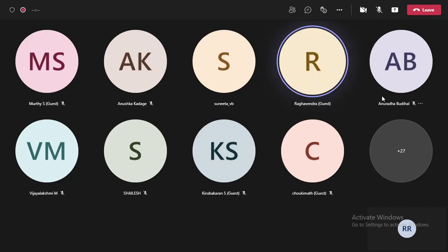Right. Okay. Good afternoon, everyone. It's Raghavendra. As promised in the morning, I'll be giving a very brief overview of how we've implemented the physical layer portion of a VLC system, where VLC stands for Visible Light Communication. So basically, in this system, we take up an LED. We encode all our information in the LED by making it blink. We then have a photodiode receiver through which we receive the actual signal, and then we're able to decode it to get our message.